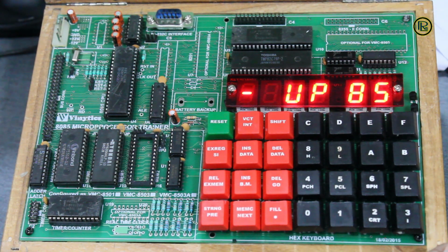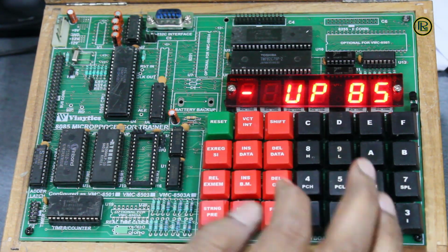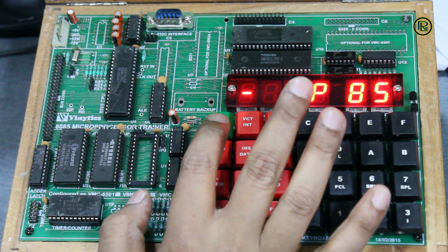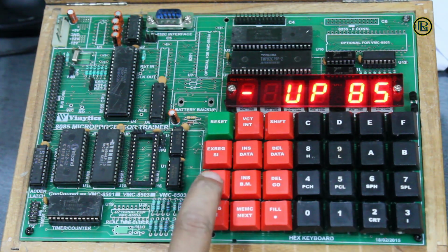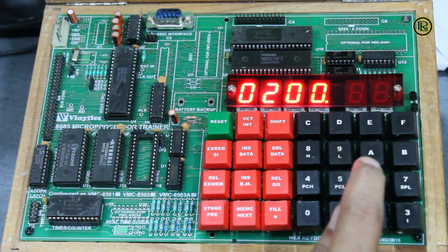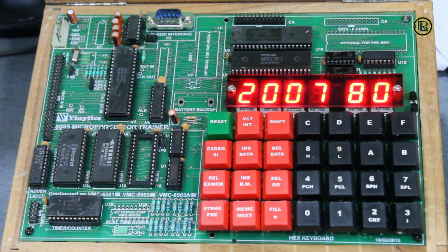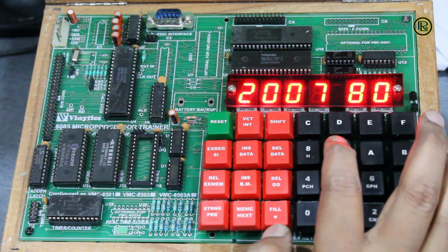As I showed you in the slide, the program is similar to the earlier one, only there is a difference in line number 7, address 2007, where instead of addition we have to subtract. So the code will be different. Now let's change that code at the address 2007. For that I have to go to memory location 2007. And what is there? There it is written 80 because it was the code for addition. Now I have to change it to 90. So I am making it 90.